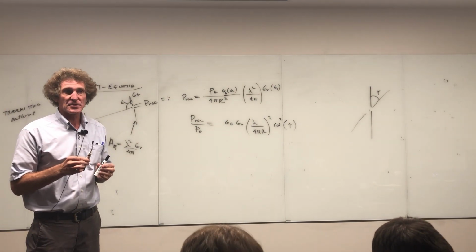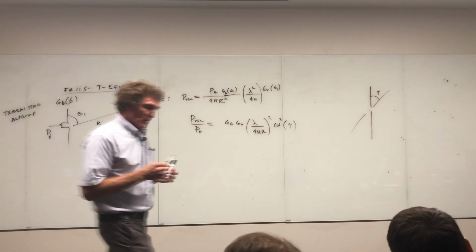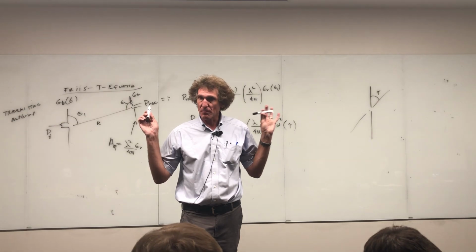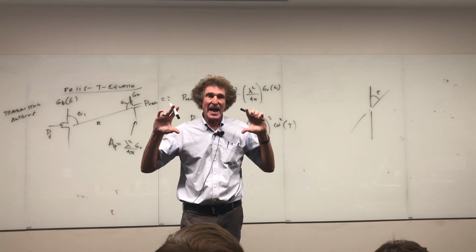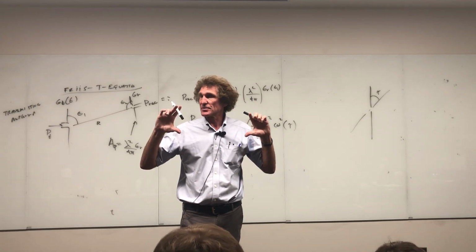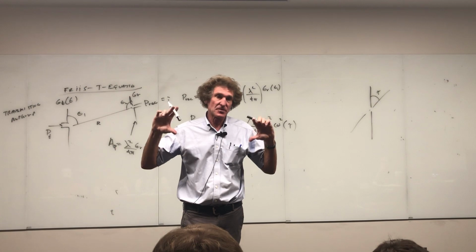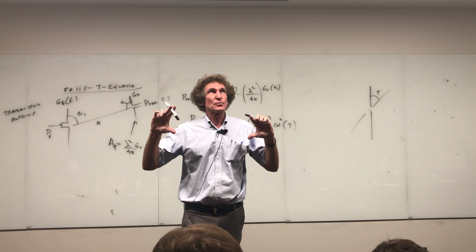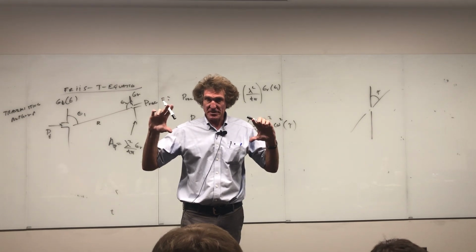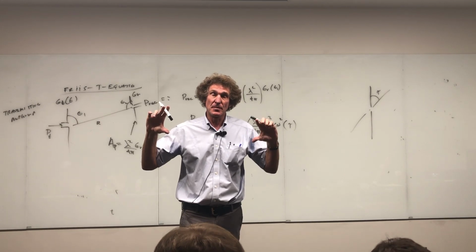I can tell you this much, that most of the time when you're talking about microwave and radar, for important things, it's circular polarization. Now, circular polarization implies you have an aperture antenna, and aperture antennas aren't affected by the tilt angle problem. Right circularly polarized, left circularly polarized, they don't have problems with tilt angle at all if it's circular polarized, or if you get an actual dish antenna that's a circular dish. There's no ellipticity to it.